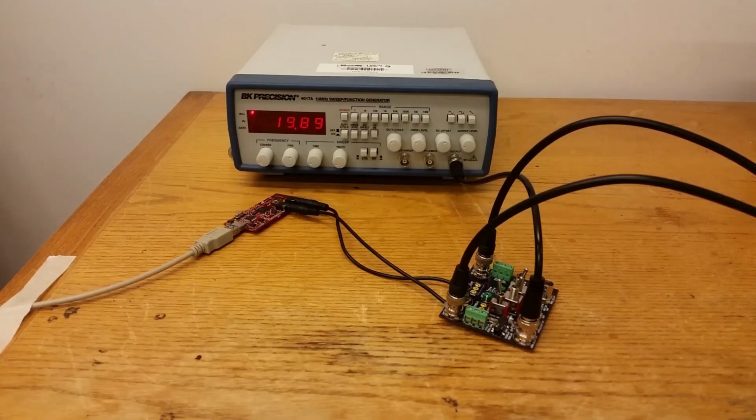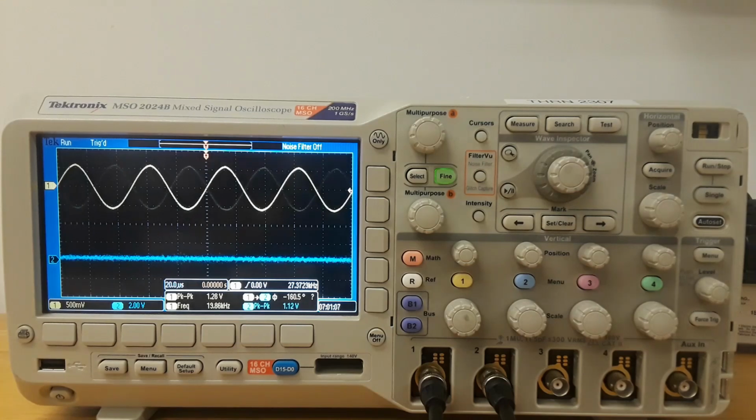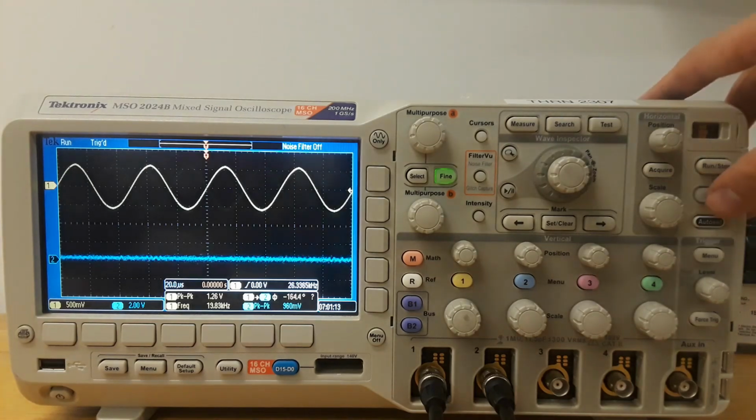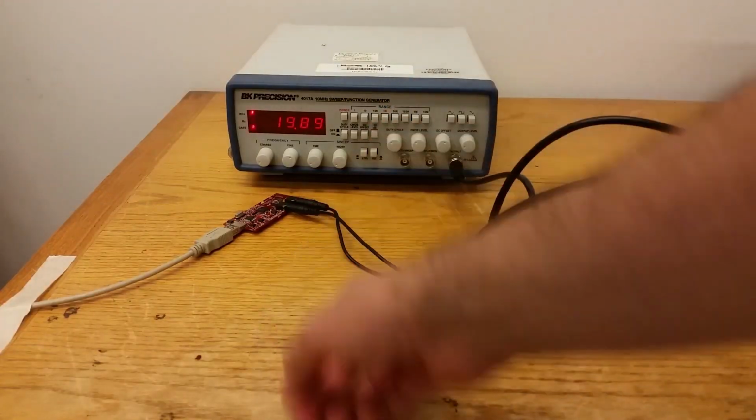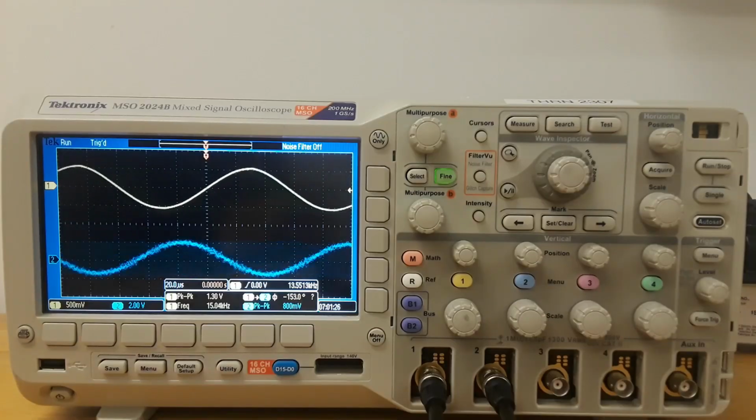So now we're back here on our 20 kilohertz input, and we're running it at a 24,000 hertz or 24 kilohertz sampling rate. So let's take a look at our signal generator and our oscilloscope again. Our input still looks the way we expect it to, approximately 20 kilohertz, but our output, well, you can see what our output looks like there. Even if we go to single, we really can't see anything more than noise. Now let's go and change our signal generator back to 10 kilohertz and see what happens next.